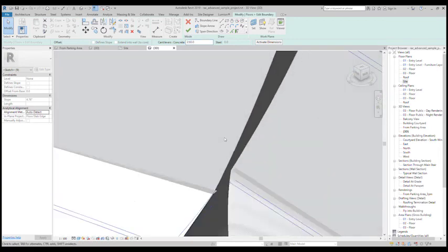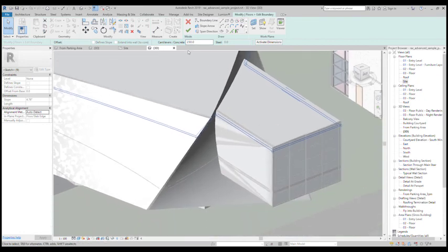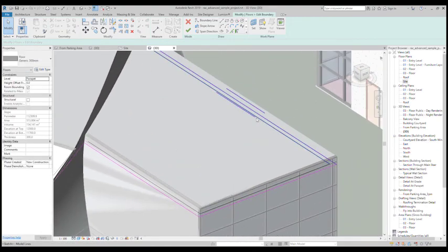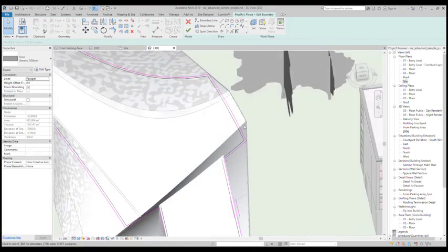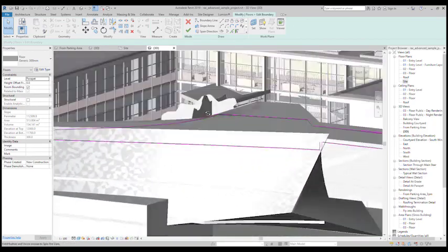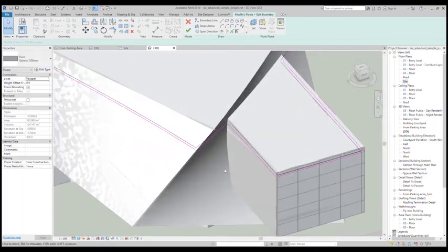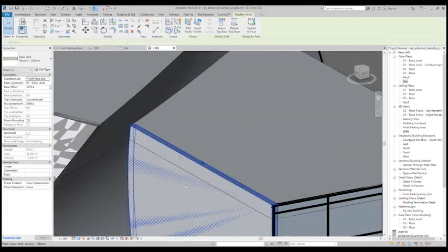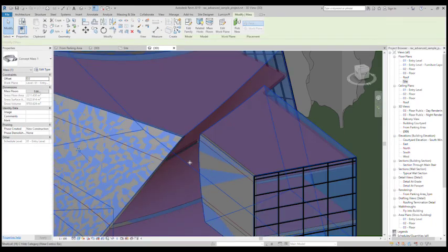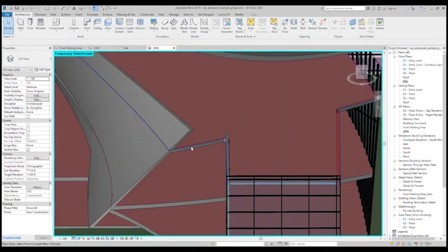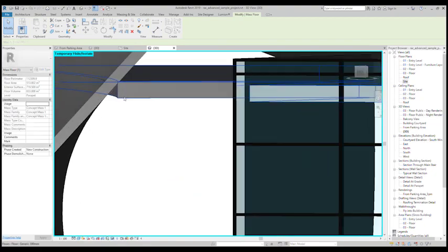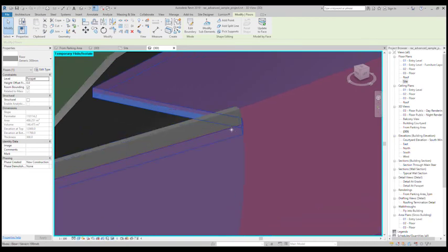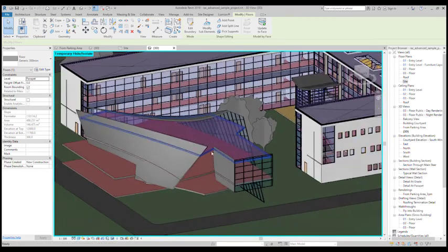And look at what happened when we put in 230 millimeters and pressed enter. Now it's showing us a new dark line on the inside of our main boundary lines, which means that these floors will always be inset now 230. So if we say finish sketch, can you guys now see that the floor is not going to the front face of the slab anymore? It's sitting now on the inside of these walls.